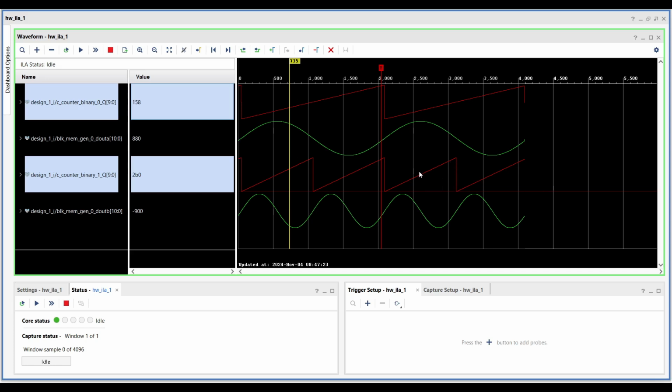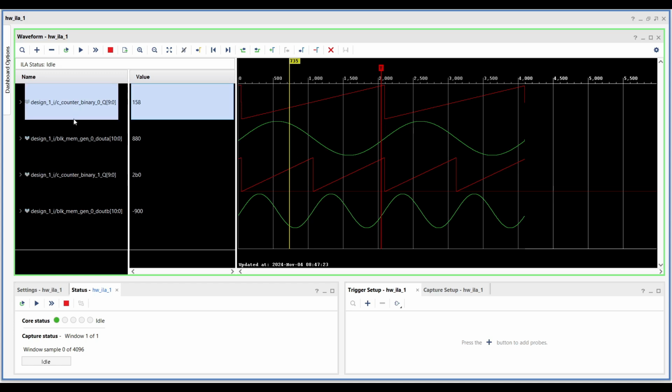In our design, we use two different clock sources to generate ramp and sine functions with distinct frequencies. Although the current counter increments by a fixed step size of 1, you can introduce flexibility by modifying the step size. This approach would allow the phase accumulator to skip values, thus adjusting the frequency of the output wave. In upcoming training sessions, we will introduce an enhanced phase accumulator and explore how an NCO can generate sine waves with variable frequencies.